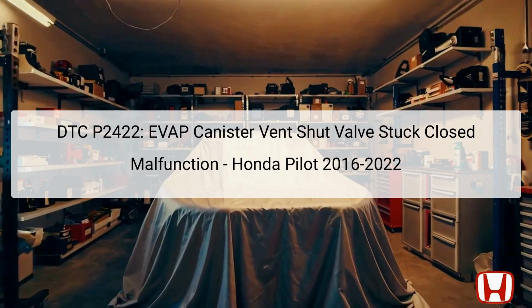The Diagnostic Trouble Code DTC P2422 refers to a specific issue within the evaporative emission control system, indicating that the EVAP canister vent shut valve is stuck in a closed position. This malfunction can hinder the proper functioning of the vehicle's evaporative system, which is responsible for preventing fuel vapors from escaping into the atmosphere.